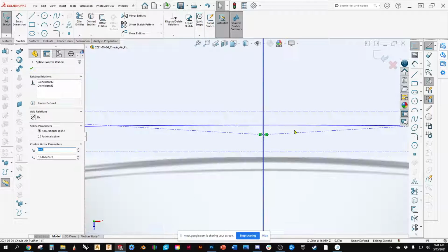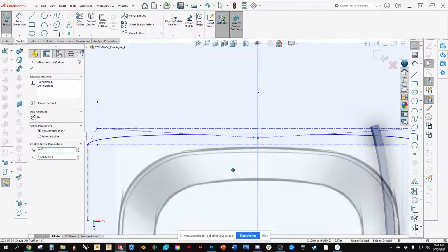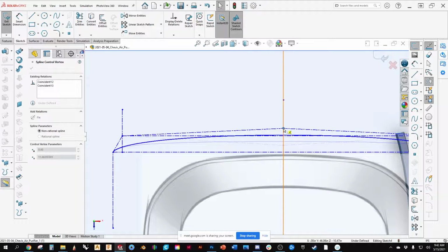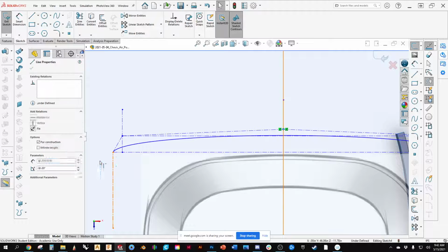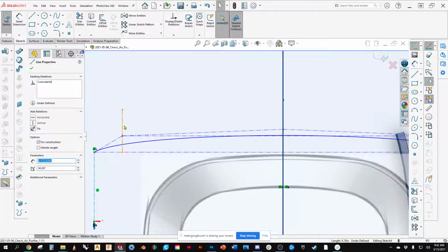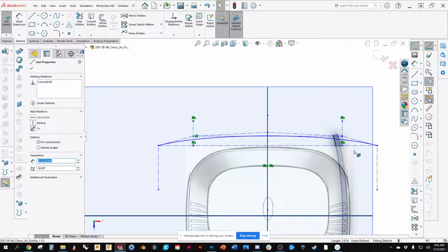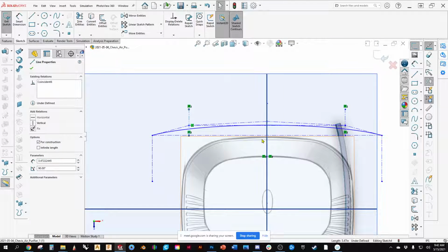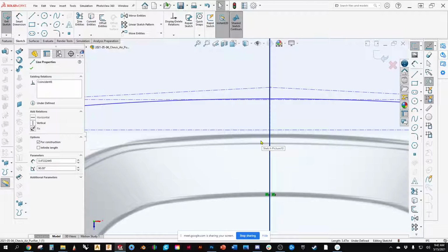And you can see right here, I know there's an inflection because my center spline, or my center point of that spline, is lower than my outside point. So that's going to give me an inflection. So we'll just raise it up. Let's just clean this up a little bit. And you'll see me zoom in and out just because I'm overly cautious. I've always got that fear that I don't have it properly defined.